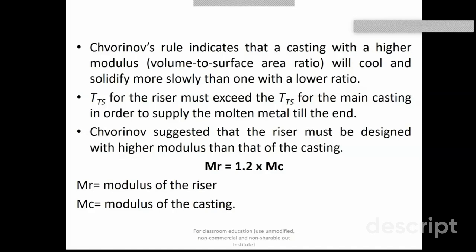Now the question arises: what should be the optimum size of your riser in case of the top riser or in case of the side riser? As we know, the surface area of the riser is a very governing factor which determines the solidification rate of the material inside the riser. So surface area controls the solidification time period, and in order to maximize this time period you need to minimize the surface area. First of all, the first thing you have to do is to calculate the surface area of your riser.